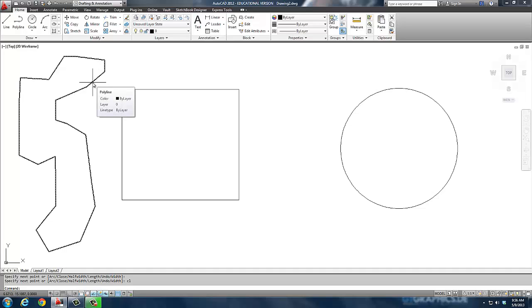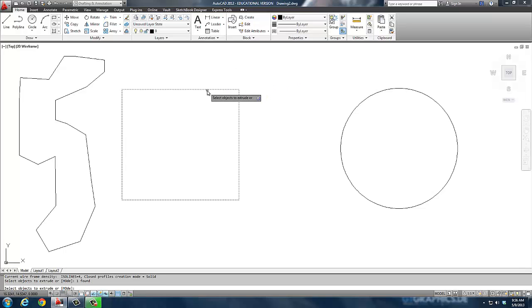Now, from there, I'm going to extrude it. So I'm simply going to go in here and type in the command extrude. Now, I learned DOS, so I still use a lot of DOS commands. There is a menu for this, but right now we're just going to stick with the DOS. So I'm going to type extrude and click on that, and now I don't know how far to make it go. I can't tell. But I'm just going to type in a distance. I'm typing 4.5.